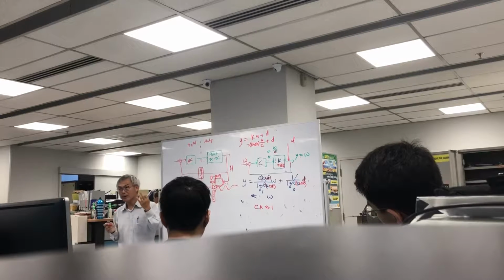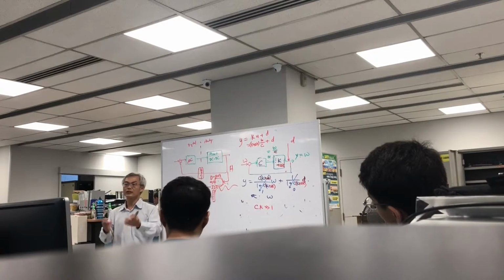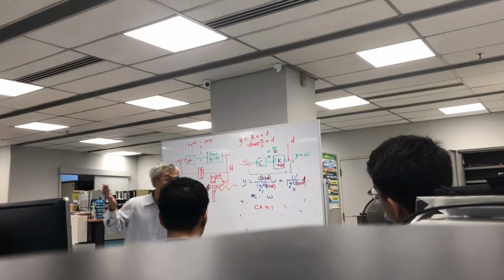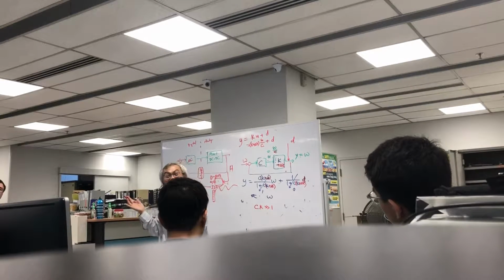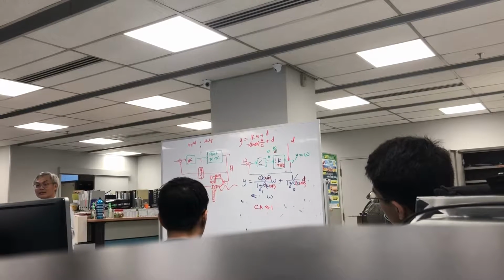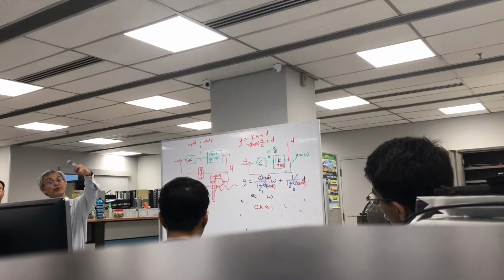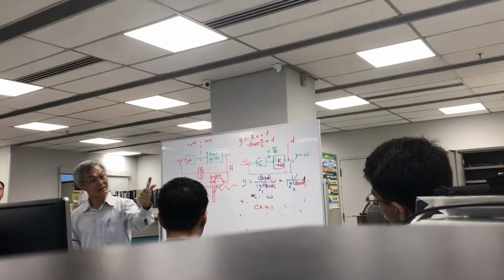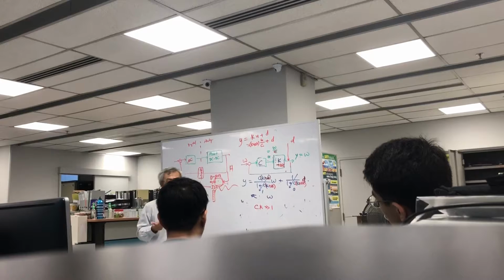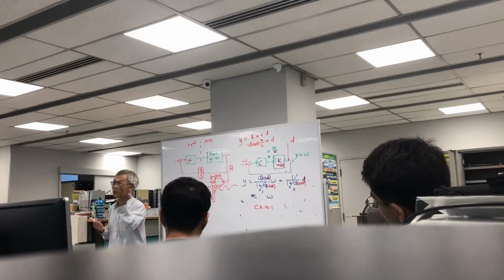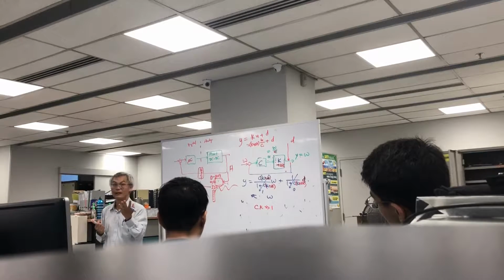Another typical situation that you will encounter is speed. How do you measure speed? Don't tell me it's a speed sensor. What's a typical situation where you need to measure speed? Of rotation of your motor shaft. How do you measure that? Tachometer. Have you heard of tachometer? It gives you voltage or whatever. Another one? Encoder.